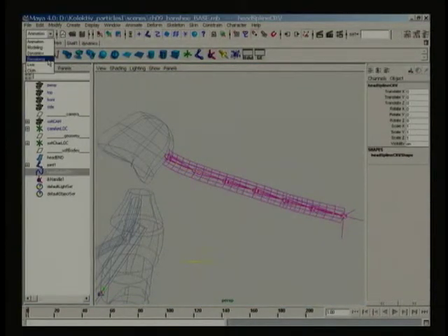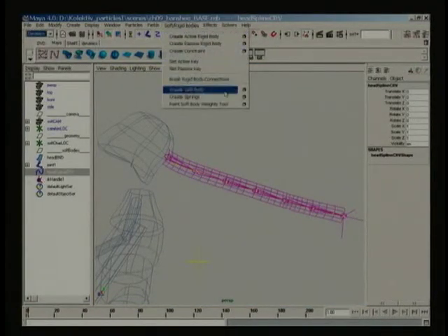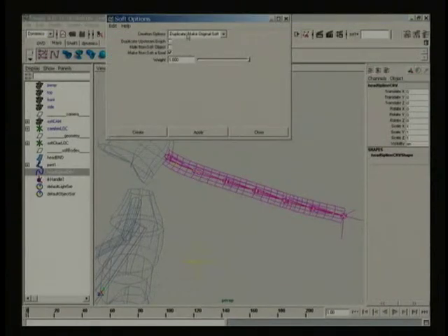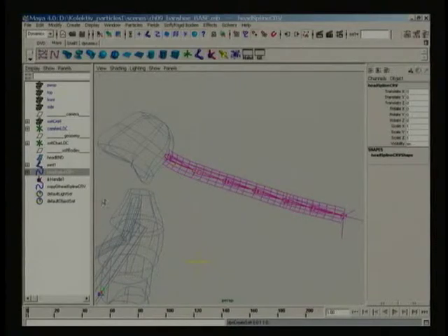Next, I'll make this curve a softbody. I'm going to set my creation options to duplicate Make Original Soft, turn on Make Non-Soft a goal, and make sure the weight is set to 1. My original curve is now a softbody that controls my joints, and I have a duplicate curve that the softbody is goaled to. I can now use the goal curve in conjunction with the softbody's goal PP attribute to control the balance between dynamics and keyframed animation.